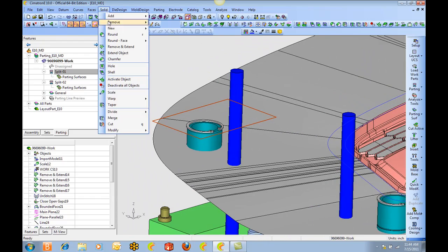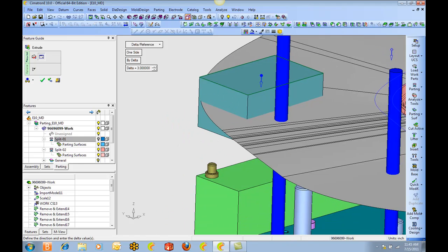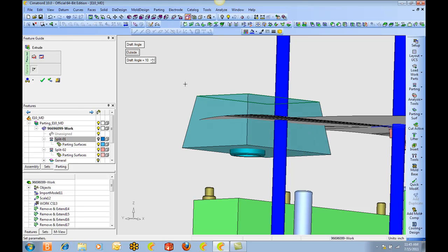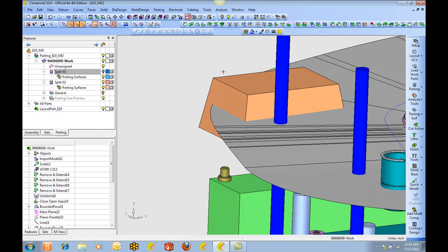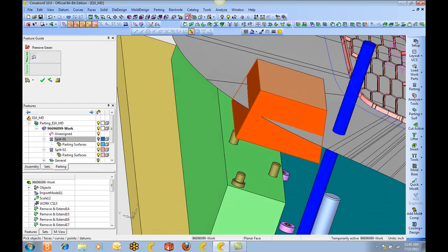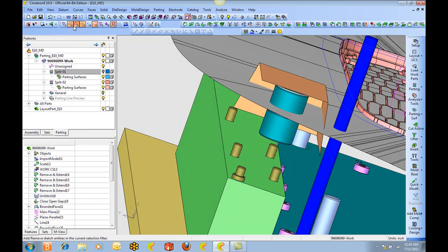Okay, then we do solid, new extrude, and let's go down 3 inches, and we're going to give it taper, 10 degrees. And then let's delete these back faces as well as the bottom face. So this is clearly an open solid.